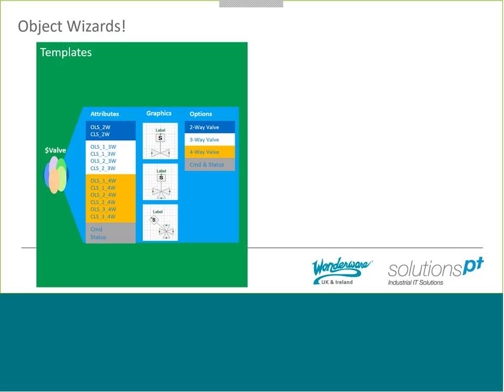And then when you instantiate that, you're instantiating everything to do with all of those valves. So if you wanted only a two-way valve, you're actually using the resources that it would take for a four-way valve. But not only that, you're getting a load of error messages because you've got item names that aren't linked up to the template, and that is creating a serious overhead for the system, and it's unnecessary.